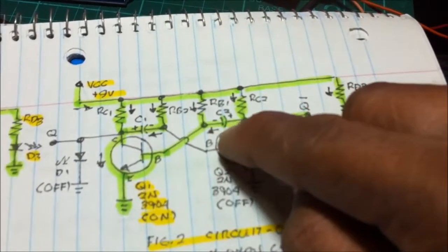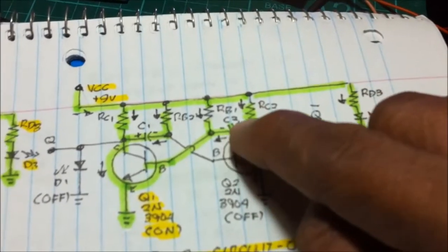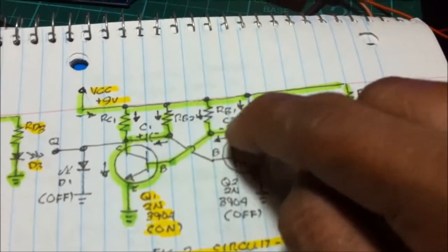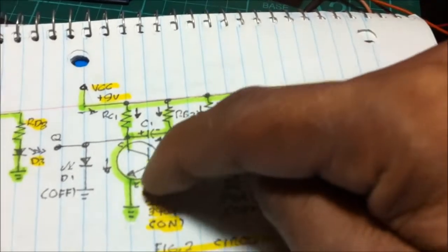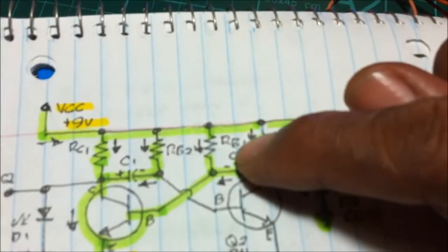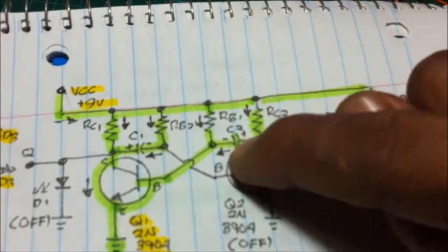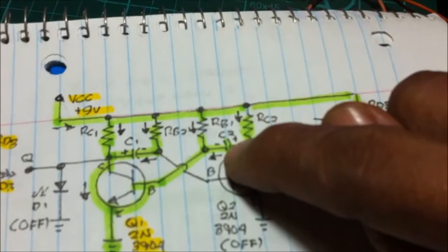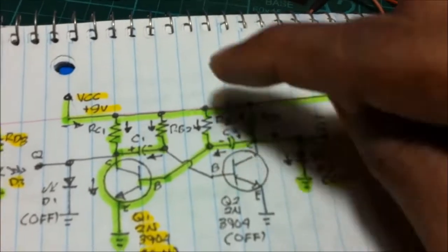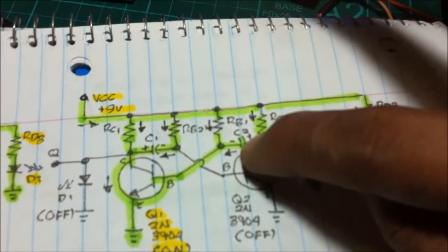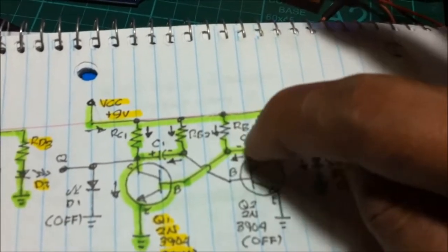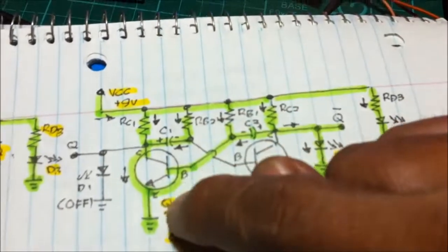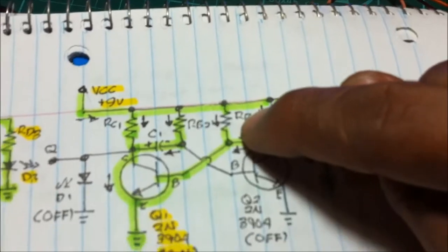What happens is when the capacitor is fully charged, it will make the circuit open in this portion. This current is now going to provide a continuous current flow from this RB1. So this one now is open. It cannot produce a continuous supply of current. Once it is fully charged, because at this state this capacitor is charging, it is equivalent to an open circuit. And what happens is the current flows into the base, forward biasing the transistor through RB1.